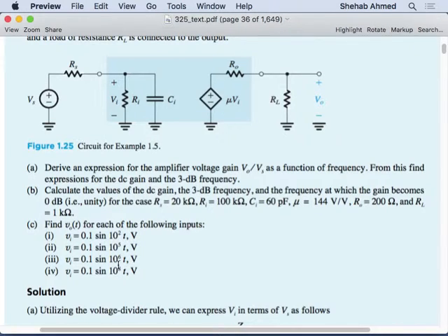The sensor's frequency is changing because it's sensing, it's converting light to frequency, right? It's converting light to a frequency of a sine wave, for example. So they're telling you, okay, what is this going to look like at the output of this system? For you to understand how it's going to look at the output of this amplifier, you have to find the relationship between Vs and V output. So we're trying to find that relation. How do you find that relationship? By finding a relationship between V output and this dependent source.